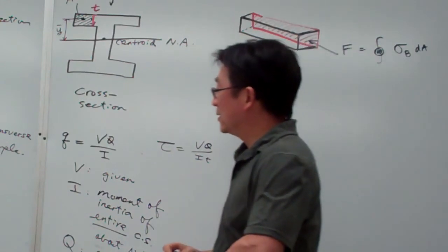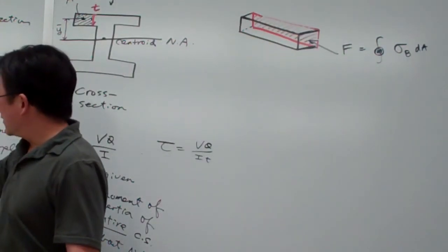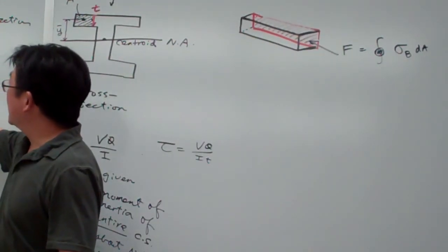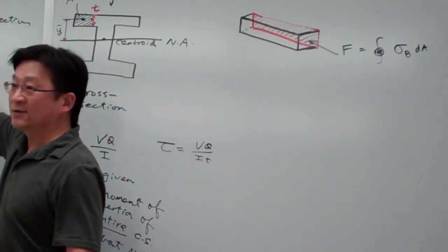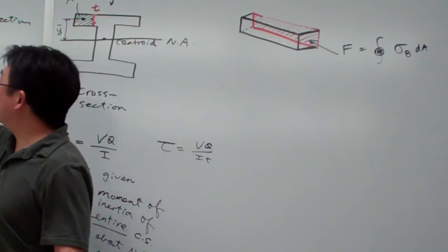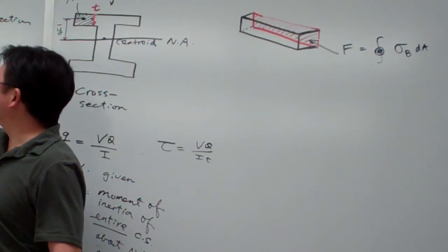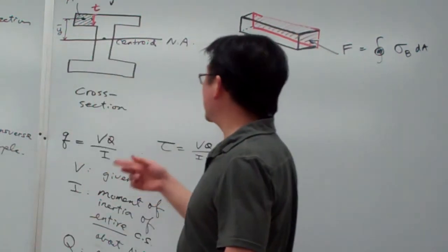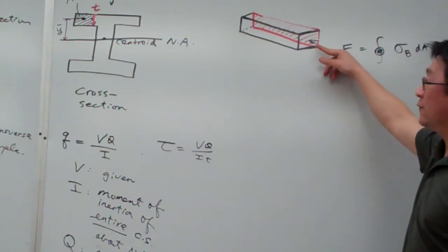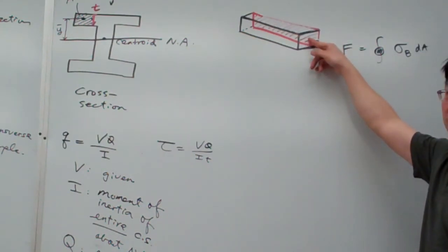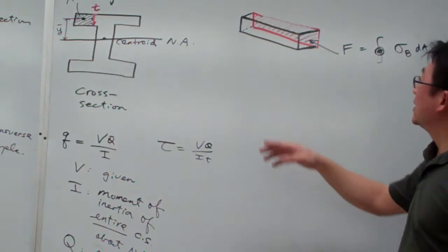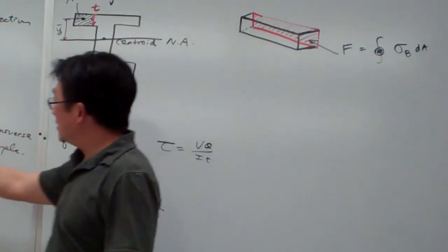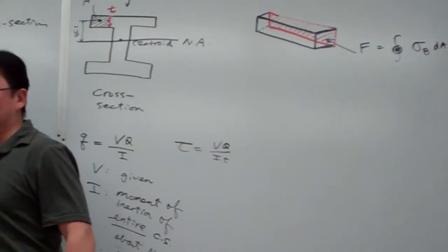Yes. Again, from this diagram, we know that the bending on this cross-section is bending like this. That means all the bending stress on this small cross-section here is compressive. The surface integral gives us the net force pointing in that direction on that area. At this end, assuming we take out the case, there is no bending.